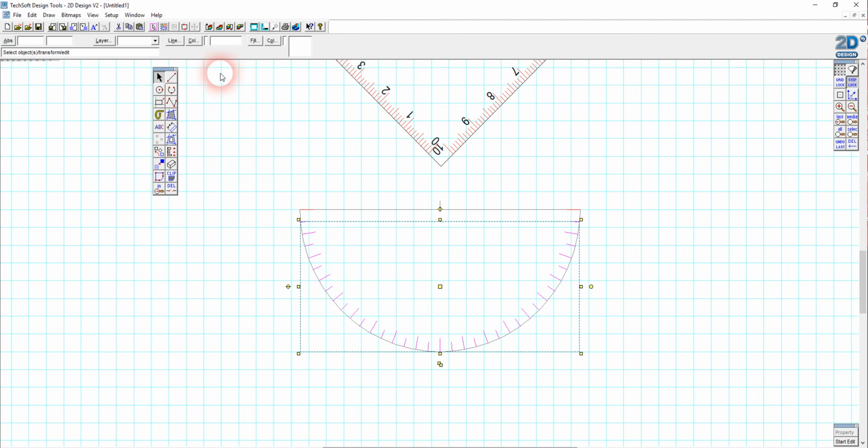So let's just select all those lines. I'm making sure I don't select the grey semicircle. Let's select all those lines. Let's come to color, red here, and now look, that's going to engrave on the laser cutter with the settings that we have here in this school. Right, let's now do the millimeter markings.